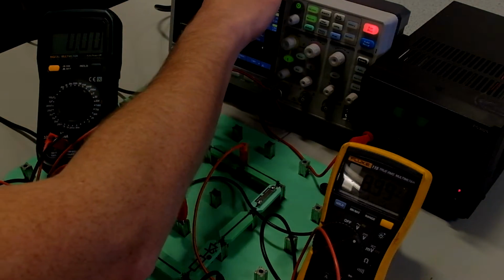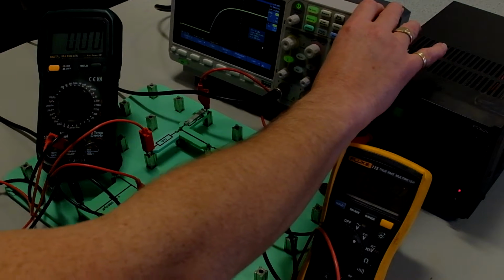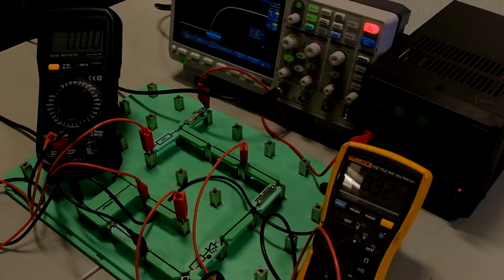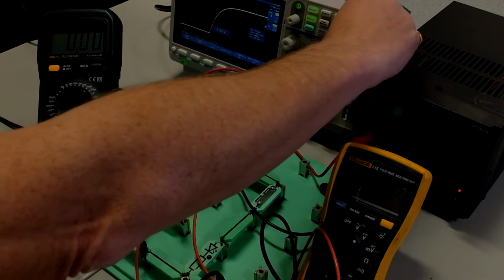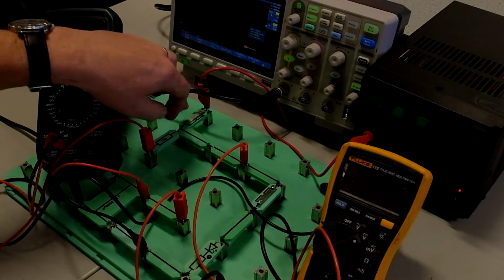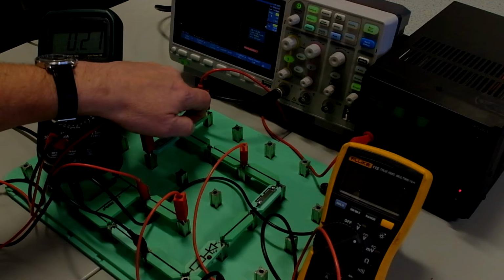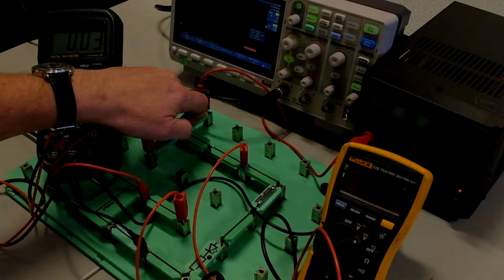and then it will come down on an exponential curve. So what we want to do now is change the trigger setup. We want the falling edge now. We want to see it coming down from 10 volts, and we want to change the trigger level up there. We want to clear it and put it in single shot. I just want to make sure it's fully charged up again. There does seem to be a fair bit of leakage. It's dropped. I just want to get it back up to 10 volts again, which it is now.